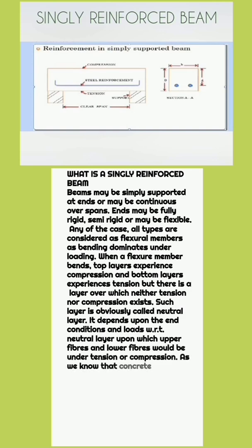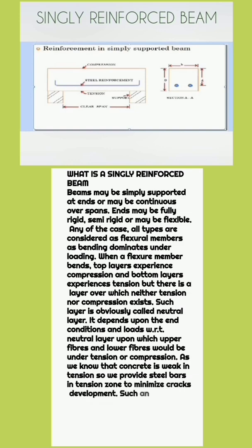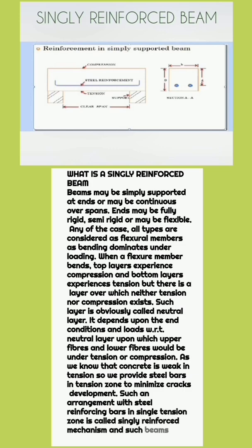As we know that concrete is weak in tension, we provide steel bars in the tension zone to minimize crack development. Such an arrangement with steel reinforcing bars in a single tension zone is called a singly reinforced mechanism, and such beams are called singly reinforced beams.